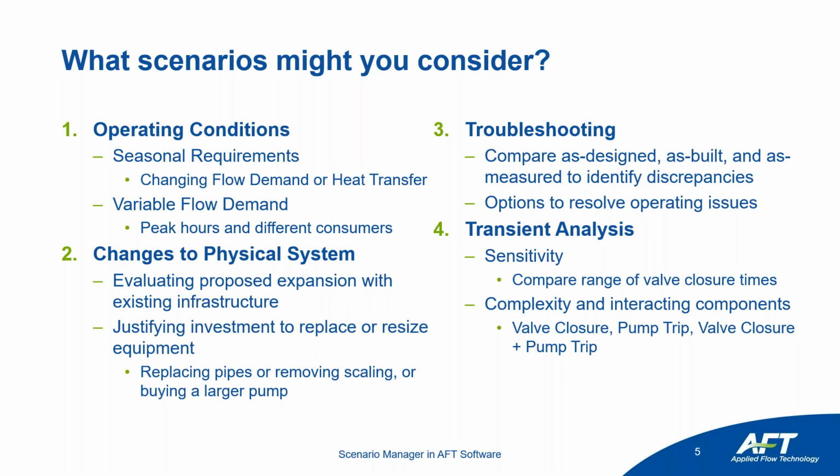And then as I mentioned, especially with more complex systems and you get these interacting components, you might have a valve closure event that you want to analyze, a pump trip event, and then what happens if you do both of those at the same time. So those are some scenarios you might consider, but anything else that you can think of, you can create as a scenario. Odds are you'll be successful building out a different scenario for each case.